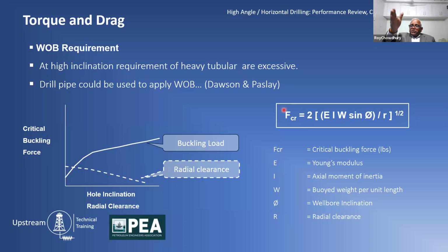It means your drill string is sitting right in the middle of the wellbore and you are applying the weight from the top. Your drill pipe is under tension, bottom hole is under compression, and all of a sudden, since you are unable to push through, your drill string starts deflecting. There are a lot of terms that they use with it. Just look at it like a snake that is going back and forth. So this is what critical buckling load is.